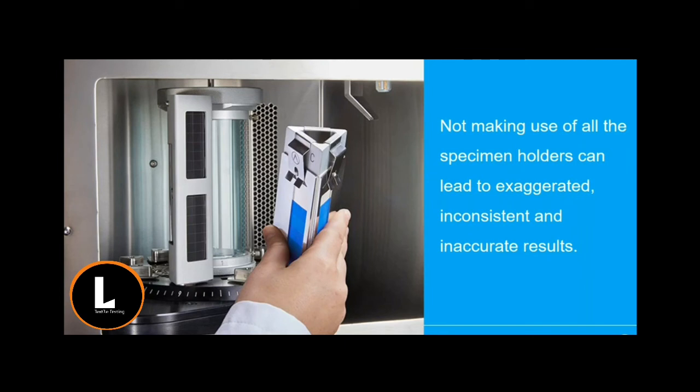If you only need to test one specimen, there is no requirement to waste additional samples. You can put blank mounting cards in, and the black standard thermometer and black panel thermometer are used to take up one of the spaces.